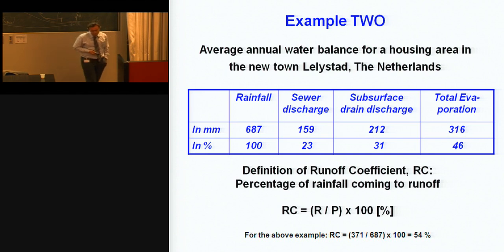Yeah. So runoff coefficients, it means that the area has to be divided, and then we have to make a cumulative runoff coefficient, because sometimes the hilly areas have so much higher runoff, but in some of the plain area the runoff is less. So it's like averaging. The way we put it here is a long-term annual average. But you can also calculate it for an event. We come to that next week, for an event scale.